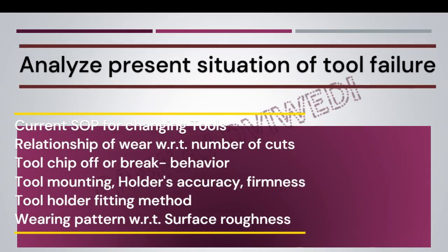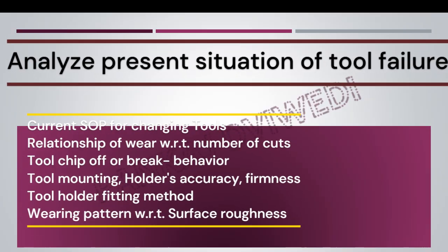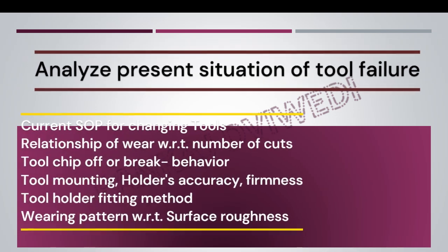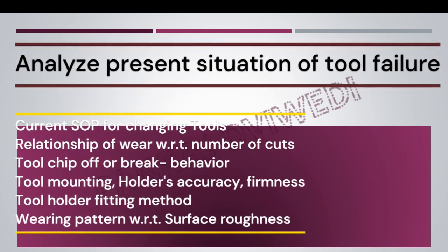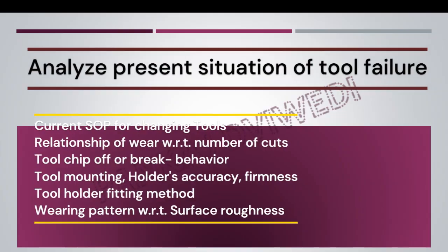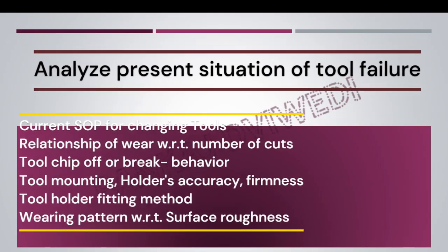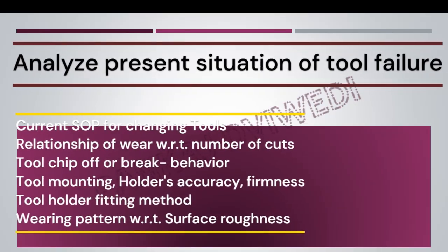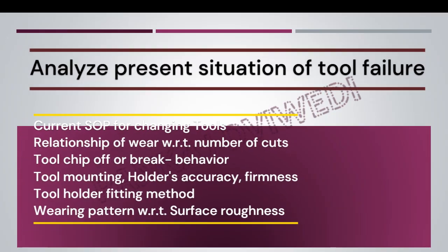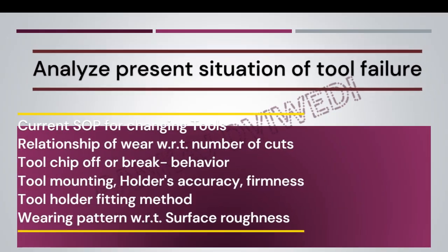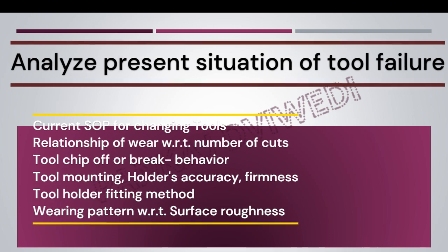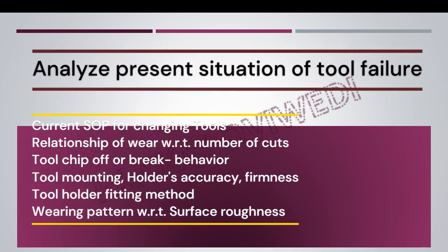Once the data is recorded, you will have a clear picture of what is happening right now. This data will help you know the current situation of failure: whether the tool is wearing out due to depth of cut, or due to surface roughness of the input material, or even while cutting, when surface roughness increases, then it wears fast.